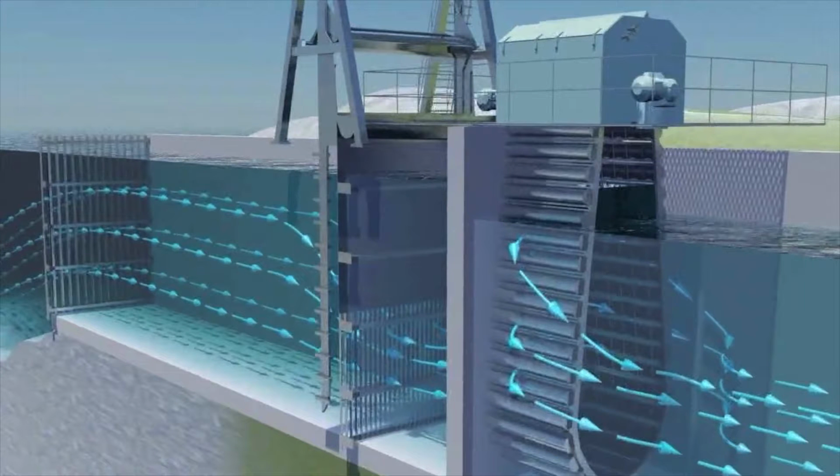This process consists of many unit operations. The first unit operation is inlet screening. The main objective of inlet screening is to remove large objects such as rock, plastic, or paper to prevent damage to downstream equipment and piping. There are two types of this unit operation.